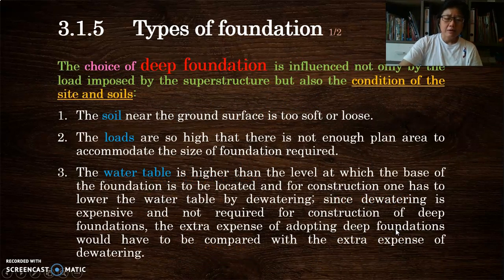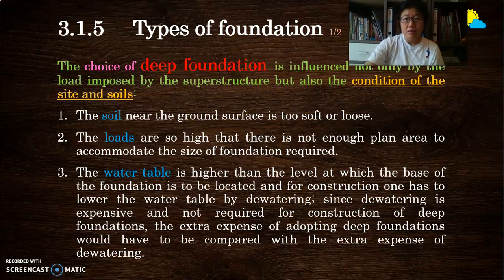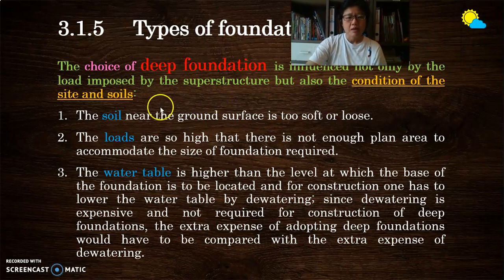Alright, now the next set of criteria we want to look at is when we want to pick a suitable deep foundation. Now, the choice of deep foundation is influenced not only by the load, but also by the condition of the site and soil. Bear this in mind. This is important to remember. Okay. Now, first criteria: the soil near your ground is too soft or too loose. So, a shallow foundation is out of the question. You need to bring the foundation down to greater depth so that the load can be sustained by the ground.